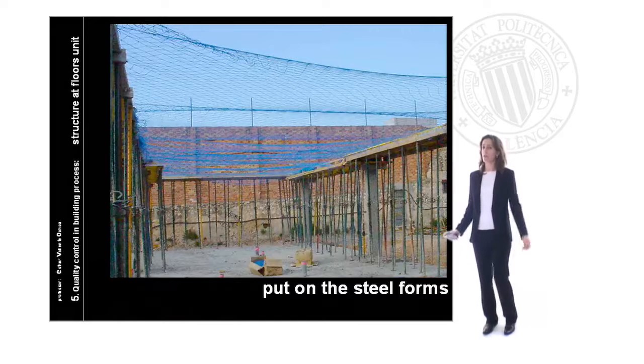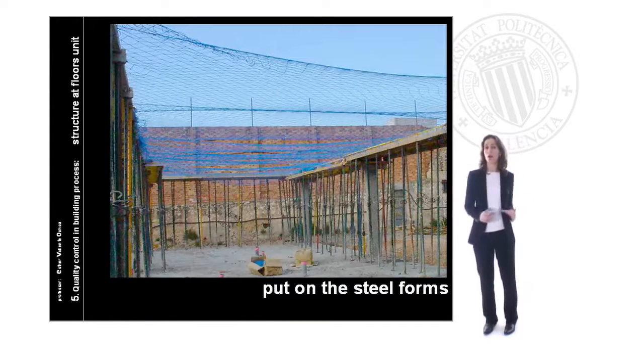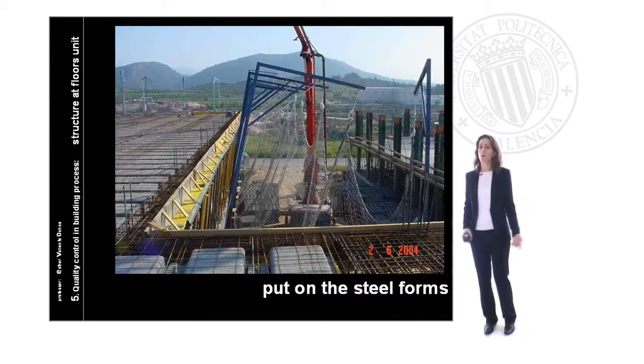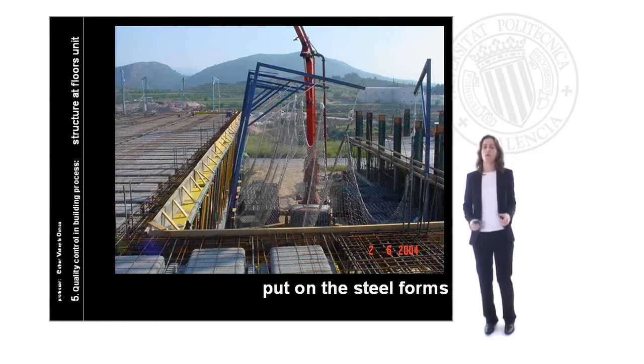Steel forms, unfortunately, are not always used for the whole surface. In some cases we can find steel forms or wood forms, in this case for beams and perimeter beams, and we have only a net in the middle area where prefabricated elements are going to be. Steel forms include too the vertical perimeter form that will support and will make the width of the floor.